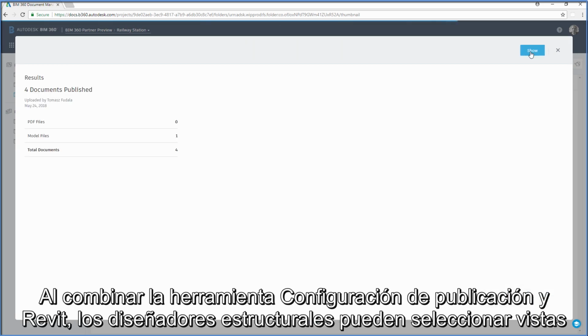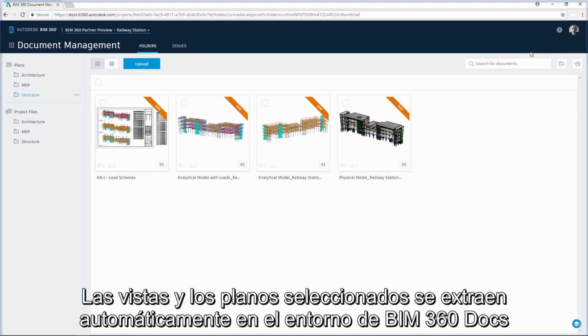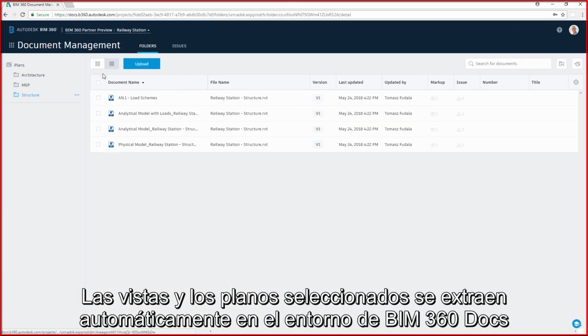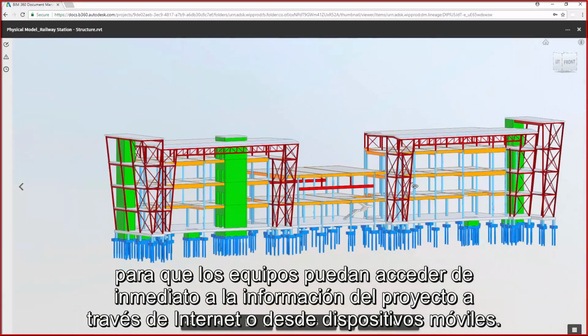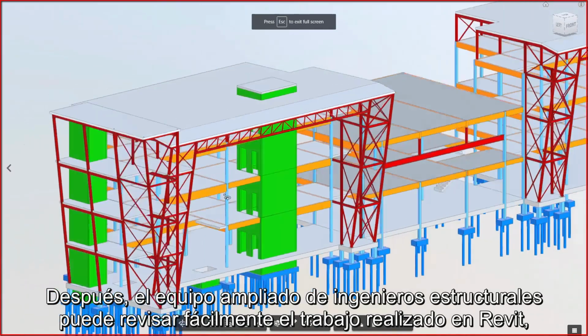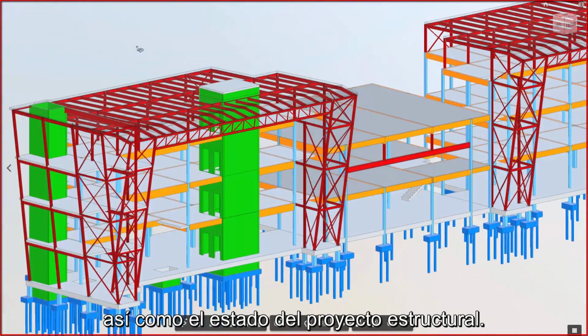Structural designers can use the Publish Settings tool in Revit to select views and sheets of the model to publish them to the cloud. These selected views and sheets are automatically extracted in the BIM 360 Docs environment to give extended teams easy and instant access to the project information via web or mobile. Then, the extended team of structural engineers can easily review what has been done in Revit and the current state of the structural project.